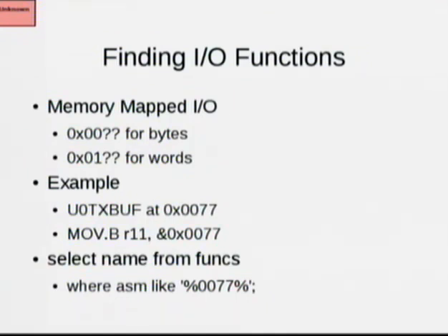If you know what's plugged into that port, which you can easily find by looking at the board and tracing the wires, then you can tell that this, say, transmits a byte to the PC, or this transmits a byte to the radio. And then you can give it a name.